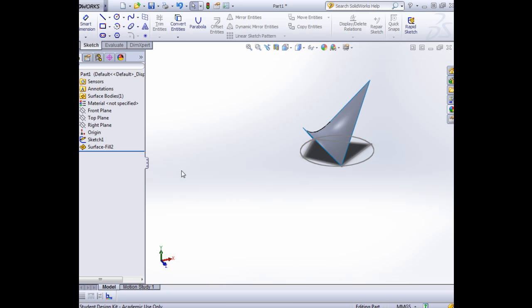A little tip: when I use this feature, it will draw in all the lines, but they'll all be individual sketches down along the bottom here. Say I wanted 6 generators going in one direction and 6 in the opposite direction, you'll end up with 12 sketches down here, which is a bit of a pain. It'd be lovely if they were all in the one sketch. A handy way to create that is to open up a 3D sketch first, before I start this, and it saves them all in the one sketch. You can see we're in sketch mode because we have our little tick over here.